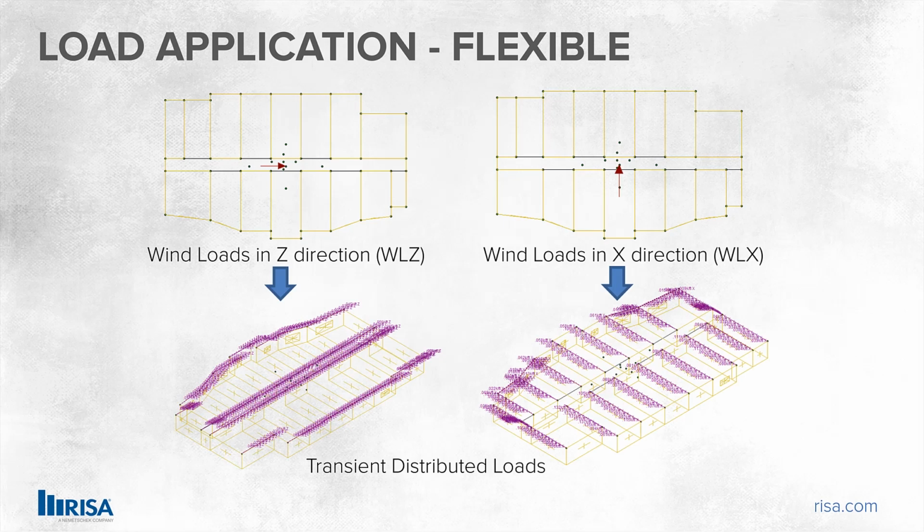These transient distributed loads are simply a reminder of how the overall load, whether it's a point load or an area load, is broken down and distributed during the solution in RISA-3D. So it's really just another kind of check to see, okay, I had this one point load, and then that point load got broken down into these points, and so they can see maybe the chord forces and how this load is distributed. So it allows you to check and validate these results much more easily.